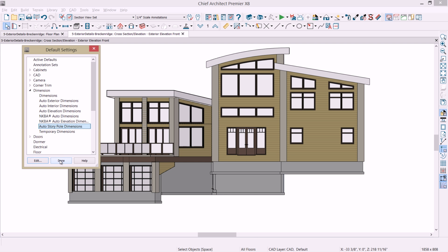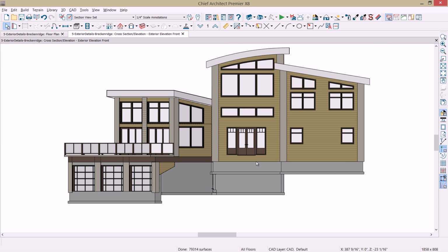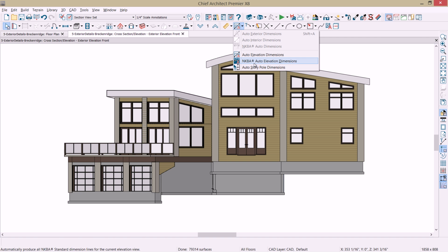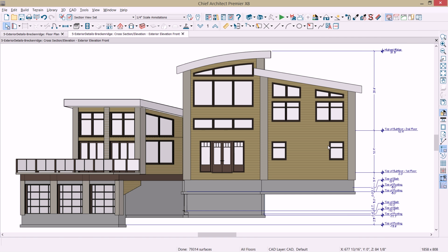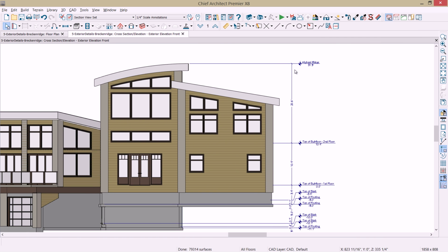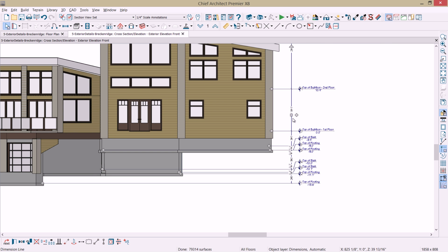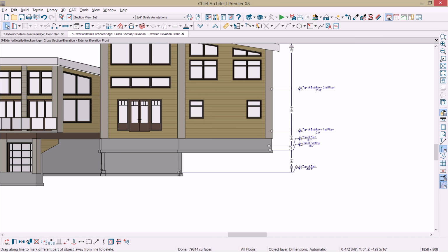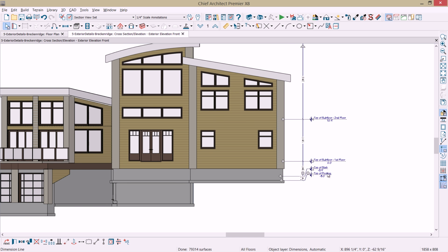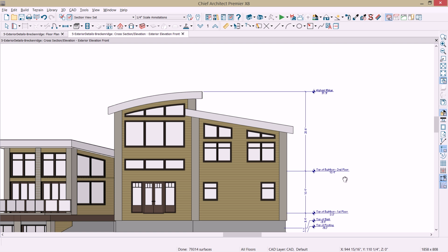As it is now, I have quite a few segments of foundation down here, and it's probably going to pick up several, and then we'll just do some cleanup. So I'm going to place those dimensions, and you can see where it's placed some of these elements in here. And to clean these up, just like the other dimensions, you can simply come in here and pull these diamonds off. It's a fairly complex design with this front elevation with all the different segments on here. And once I have this cleaned up, you can see the segments. You can drag these on here.